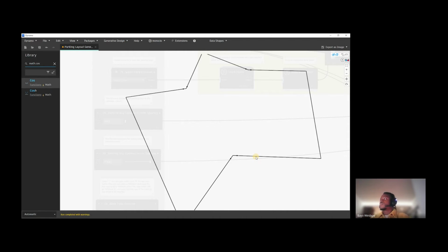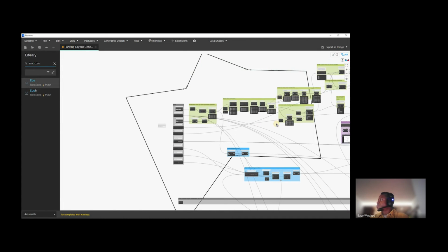So the more difficult thing to work out is the concave corners, because if you do not set those correctly, I mean, at the convex corner, the parking bays are never going to clash. But if you do not set these out correctly, you can imagine they start to clash with each other. You can't set out the parking bays at the concave corners from the starting point there, or else they meet each other. Okay, so I'm going to show you what I'm talking about.